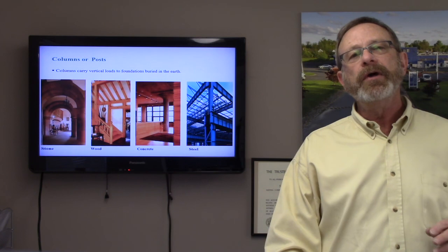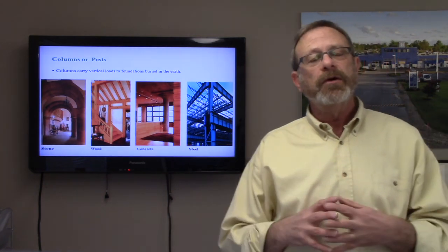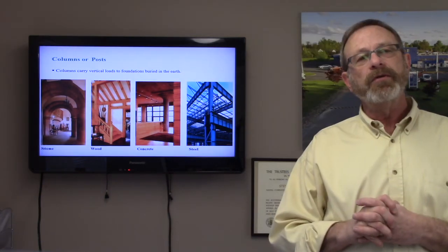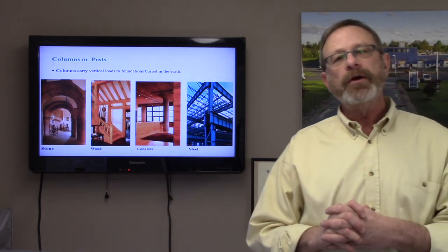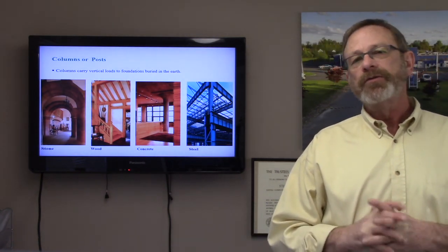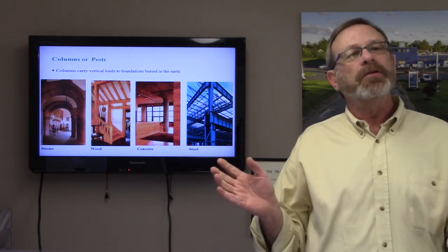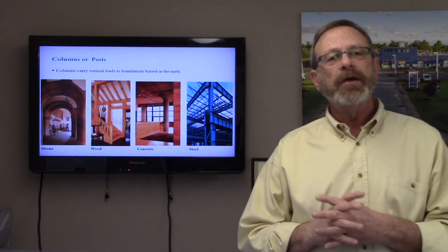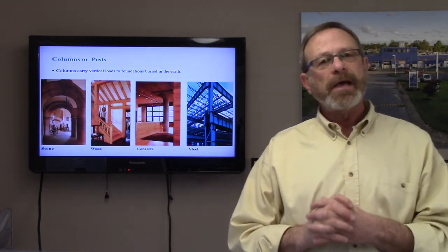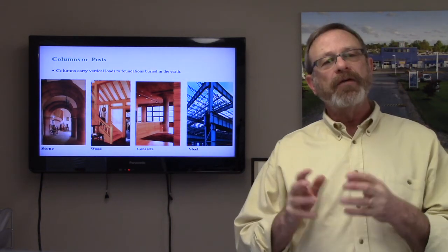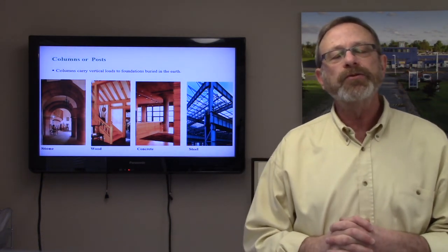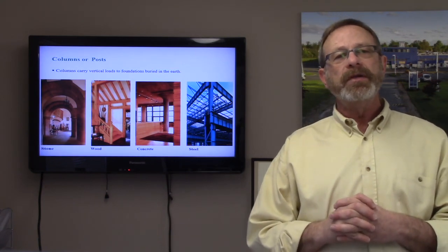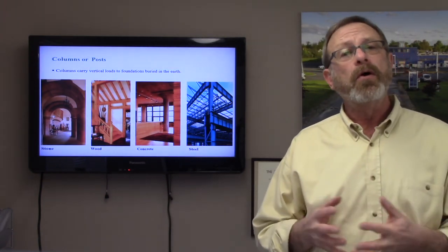Therefore, it is very important to understand the intrinsic nature of the soil type. Soil types can vary tremendously as to their capacity to withstand load. So what do we do? We're going to call the soils engineer, and he's going to come out with some equipment and test the soil and find out what type of soil it is, and find out what the bearing capacity of that soil is, and what needs to be done to either increase it or augment it.